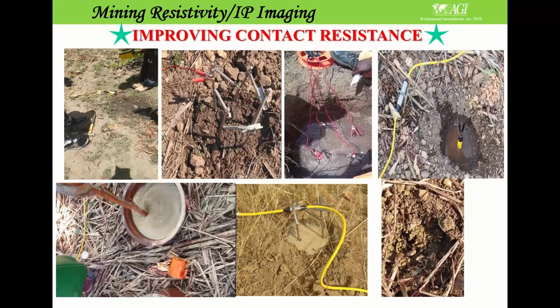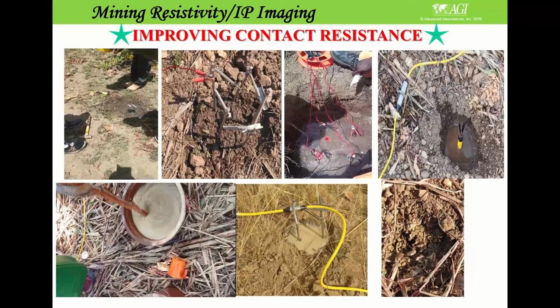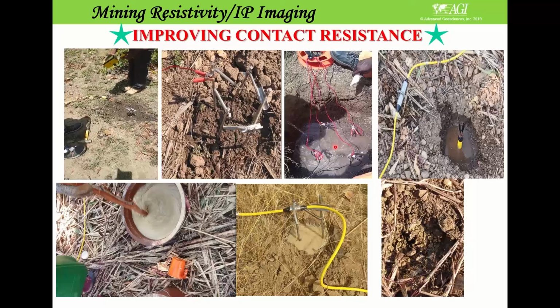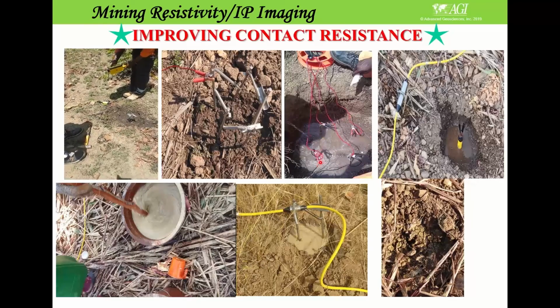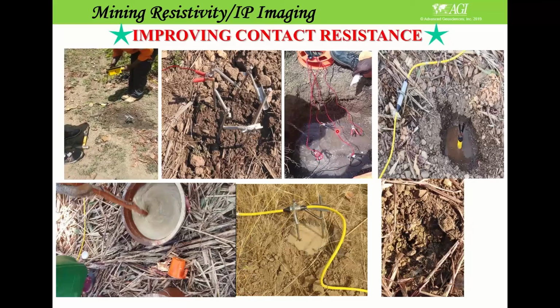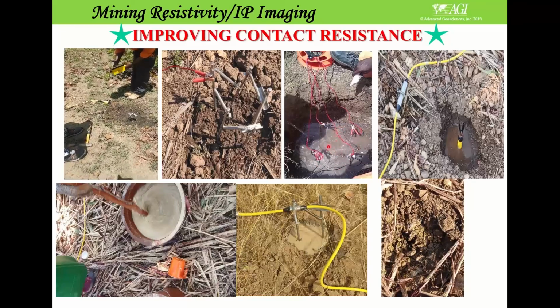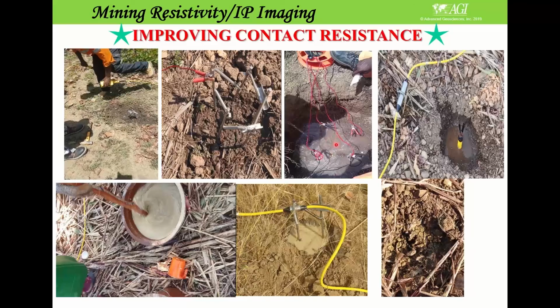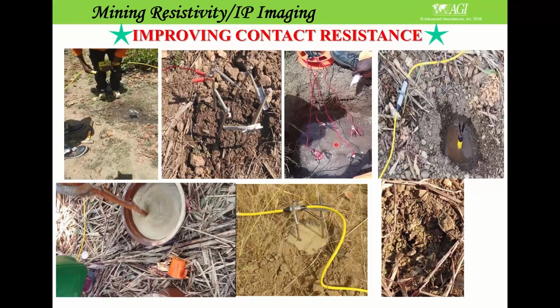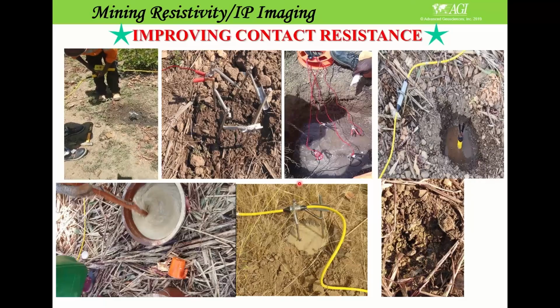Let me just go pen laser over here. If you do this for the pole electrode locations, and then dig a ditch like this and put lots of water, salty water, or bentonite solution, whatever you have, because this electrode in a pole-dipole measurement is used for current injection for every measurement, okay?